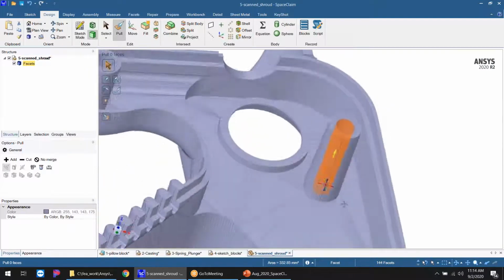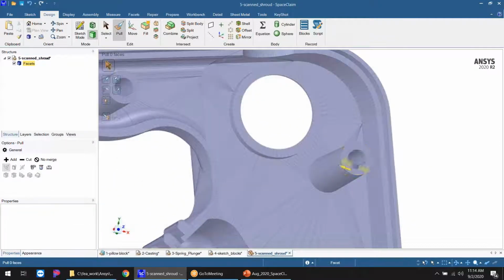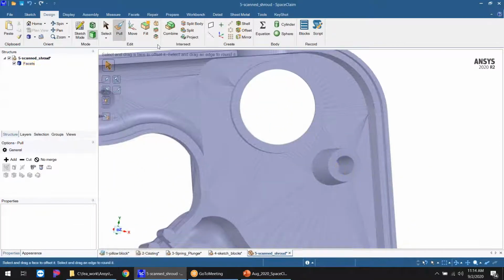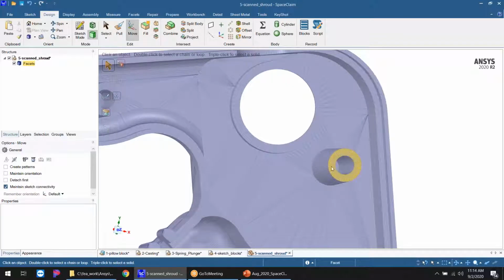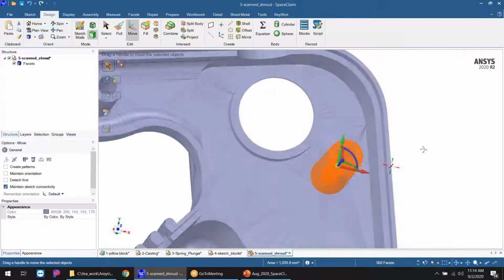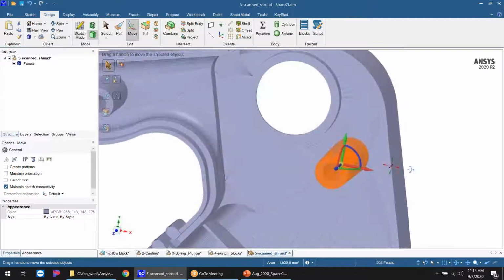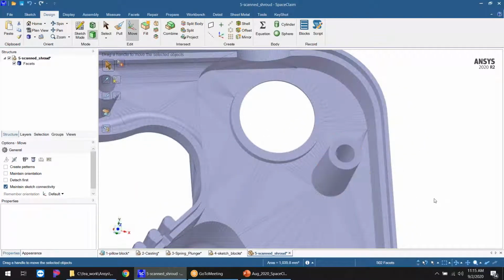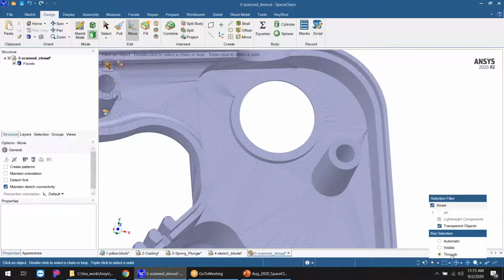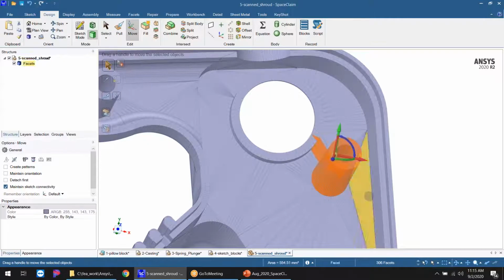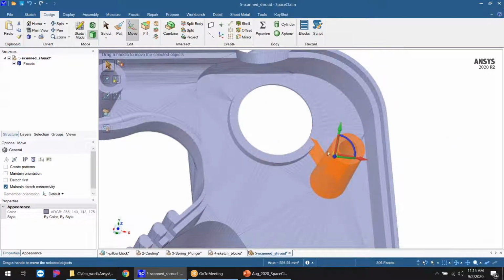Another thing I can do, and again, this is in conjunction with the selection tool. If I wanted to box select, and let's say this boss, I wanted to move down here. If I box select that by default, I'm grabbing everything there, I have that option turned on. You're probably thinking, how did it know what to grab? Let's talk about this. Down here, I have a through. If I change box selection to automatic and I grab that, I'm only grabbing what is in the box. I'm going from left to right.